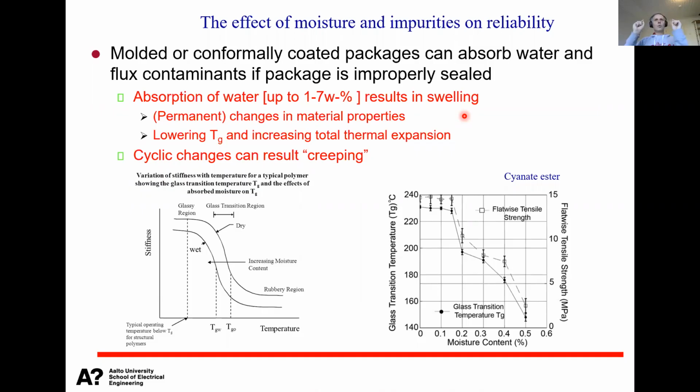And when these water molecules are diffusing, absorbing inside the polymer, the bonds between the polymer chains are getting looser. It results in swelling. Swelling is kind of the same thing as when you increase the temperature and the materials expand because of the coefficient of thermal expansion. But swelling is the same thing, changing the volume because water is going in.